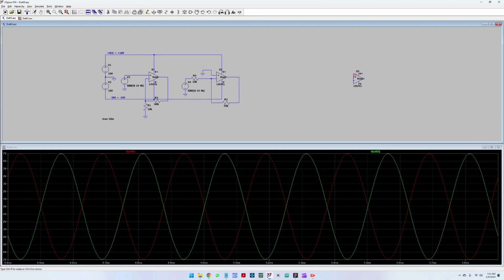So I'm going to copy the operational amplifier. I'm going to copy the signal, the sine signal for the input, and I'm going to copy one power supply and the ground for the power supply here. Okay, so let's connect the single supply here. So we are connecting to the V plus, and the minus value is V minus, or the negative voltage. We're going to connect it to the lowest voltage level that we have, which is ground.